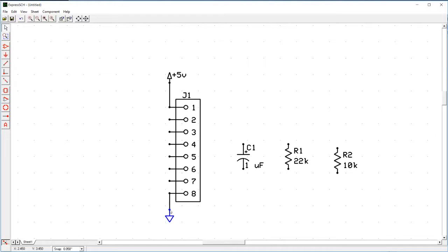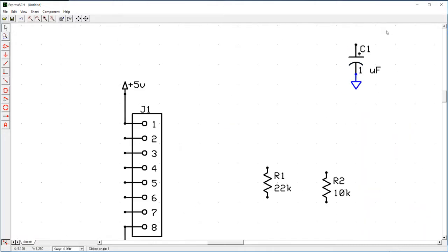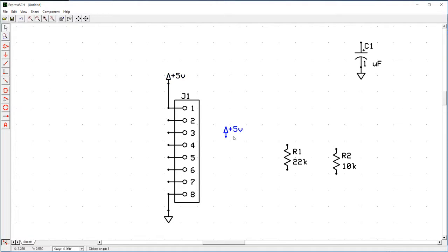And I can also include, so for example, I don't need my capacitor in any particular place. I can put ground and copy paste. I can put 5 volts on my capacitor, and that's fully wired up, and it's clear that that's ground and 5 volts. So I don't need to make all of my wires messy. If I have an element that's over here taking 5 volts and ground, I can give it its own 5 volts and ground. I can also use tools over here to place a wire. And so that's the other thing that might be helpful.